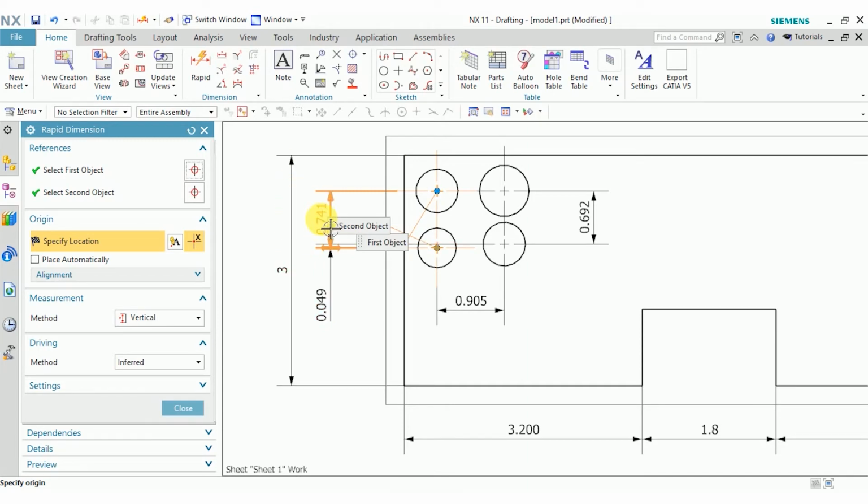And sometimes that's a really useful way to keep your drawing organized, but sometimes for those really crazy, gnarly drawings, it's just going to mess you up. All you have to do is hold down the Alt key, and now I can move this dimension around and place it pretty much wherever I want.